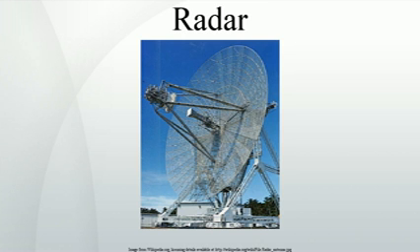So each radar uses a particular type of signal. Long-range radars tend to use long pulses with long delays between them, and short-range radars use smaller pulses with less time between them. As electronics have improved, many radars now can change their pulse repetition frequency, thereby changing their range. The newest radars fire 2 pulses during one cell, one for short range, 10 km/6 miles, and a separate signal for longer ranges, 100 km/60 miles.